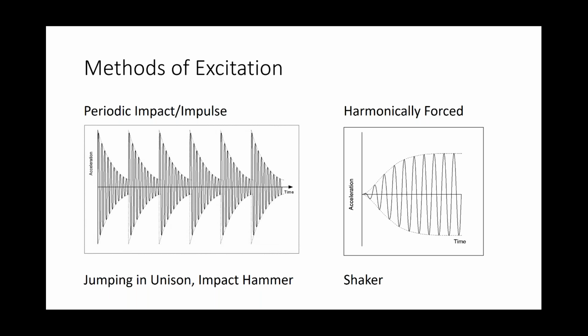The other thing you can do to get better results is employ forced vibration. You employ a harmonic forcing, and now you've got a known frequency of vibration that you can try to match with the natural frequency of the structure. And when you're testing at resonance, that generates not just confirmation of the natural frequency, but also an ability to identify the damping parameters of the structure.